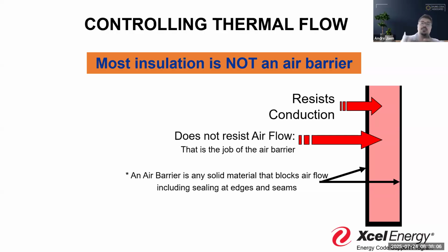Okay, well, let's take a look on the exterior. As you do this, let's see if we can seal that up better. We're going to replace that insulation, right? And we'll see if we can do some caulking, maybe some spray foam in some areas if we're going to be pulling some of that insulation out. So this is a tough question that's really dependent on the depth of the remodel.